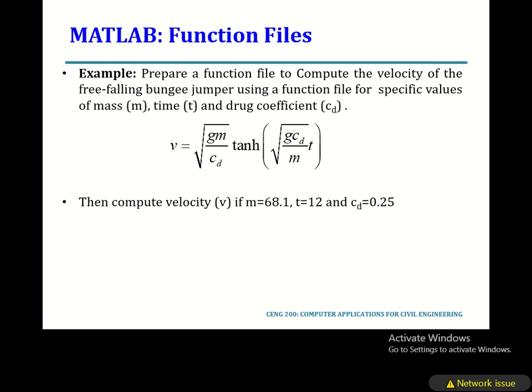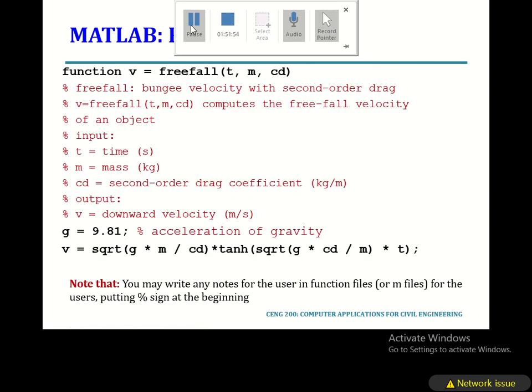You can name the function whatever you want: F, double F, F plus, F minus, my F. Add comments, so that anybody who takes this function from you can see all the comments. One more thing: if somebody wants to use this function, he will type help and ask for the function. When MATLAB opens the file, he can see the comments, and he knows what is T, what is G, and so on.